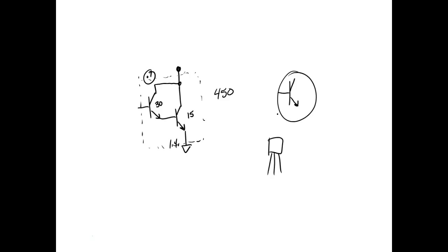So Darlington is a very popular way of hooking transistors because we get a real high beta. I mean, real high, because the betas are what? They multiply. And that's minimum beta. Odds are we would use minimum beta when we design the saturated switch, but if we were to operate this thing in the active region, like in a power supply, then the beta is going to be somewhere between there, right? That makes sense?